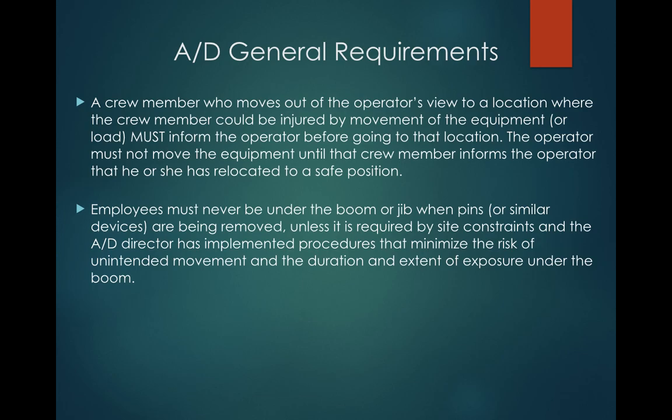Employees must never be under the boom or jib when pins or smaller similar devices are being removed unless it is required by site constraints and the director has implemented procedures that minimize the risk of unintended movement and the duration and extent of exposure under the boom.